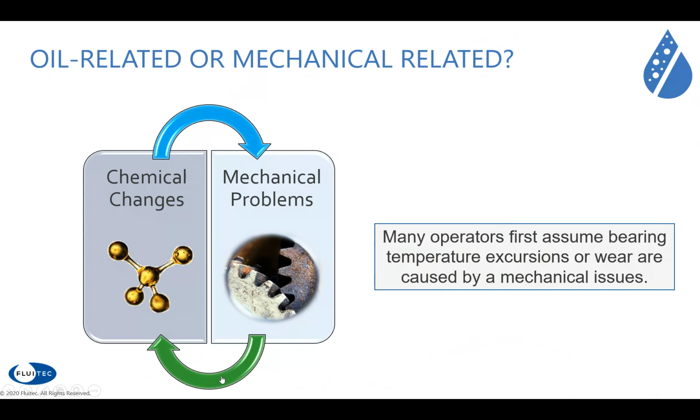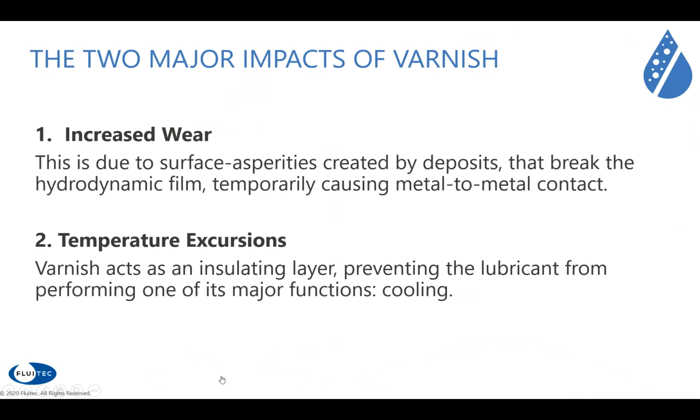And yes, I think that is typical of what we have seen in bearing temperature excursions or increases, or wear: when we look at oil analysis, we see that some changes already occur prematurely, before you can see any mechanical change. So oil analysis is again an important tool to help you see this change and detect the trend of a possible change in the condition of the oil. That can of course be very helpful for rotating equipment, as defined by your OEM specifications or ASTM standards focused on in-service oil analysis.